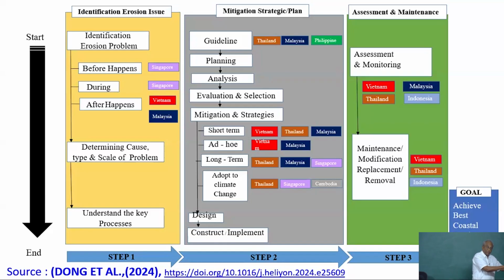This offshore bar will act as an obstruction, thus reducing the successive waves which are going to come later, and thereby resulting in the breaking of the waves slightly far away from the shoreline. What will happen? This will pick up the sand from the offshore bar and redeposit it on the coast, and then over time you may have a stable equilibrium. So, you have to keep this in mind.